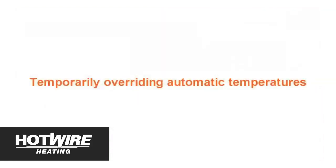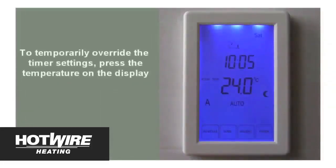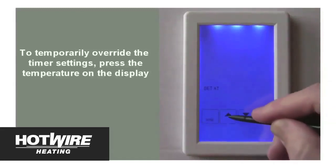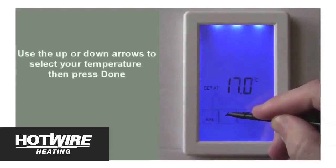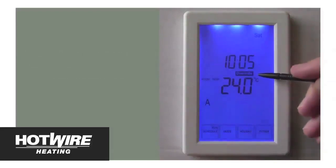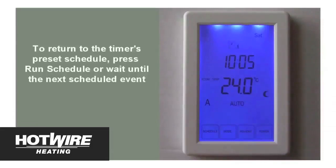Temporarily overriding the automatic temperatures. If you wish to temporarily force the unit to warm up or cool down at any given moment, simply press the temperature shown on the display. Then choose your desired new temperature and press Done. The override symbol will display and the unit will stay this way until you either press the Run Schedule button or until the next scheduled switch on or switch off event occurs in the unit's timer.